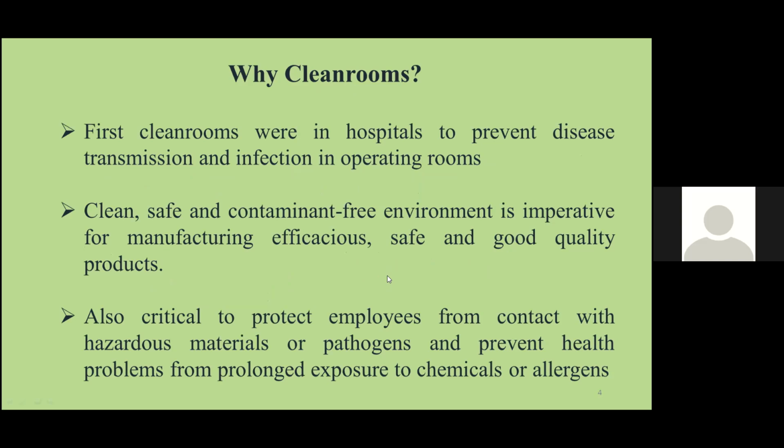So we need a very clean environment, because everybody knows the microorganism size is about 0.5 micron to 5 micron. These are the particle sizes responsible for the contamination of the product of semiconducting devices, or some biological or pharmaceutical materials. So for those materials, we need a clean room environment. Therefore, we design the clean room for that purpose.